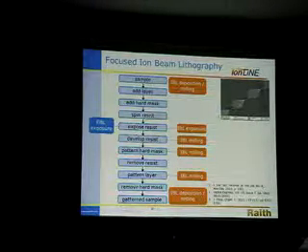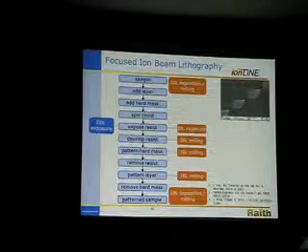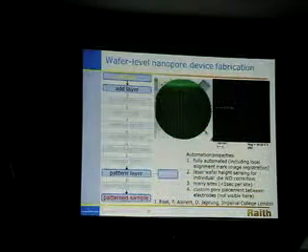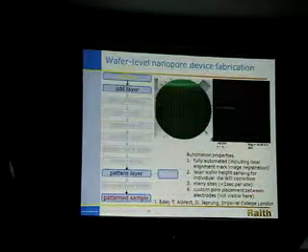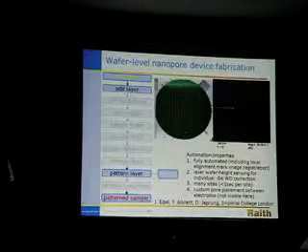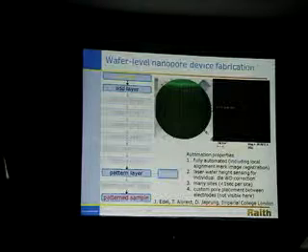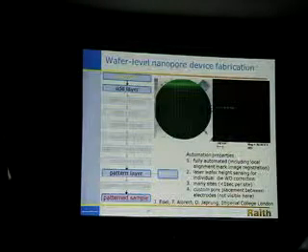This is a microfluidic channel that was stitched together over a millimeter length using focused ion beam lithography. A couple of other examples. Wafer level nanopores. This is a 6-inch wafer, maybe a 4-inch wafer. We have also taken the process up to 6-inch wafers as well.